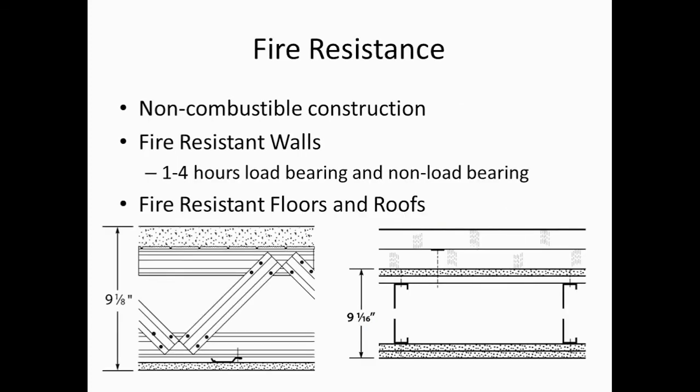Fire resistance. To me, first and foremost, all the elements that are used in the systems that I'm talking about are non-combustible. They do not support flame, they do not support fire, they do not contribute to a fire. So for that reason, let's say in wall applications, you can go from 1 to 4 hours very readily in both load-bearing and non-load-bearing applications.